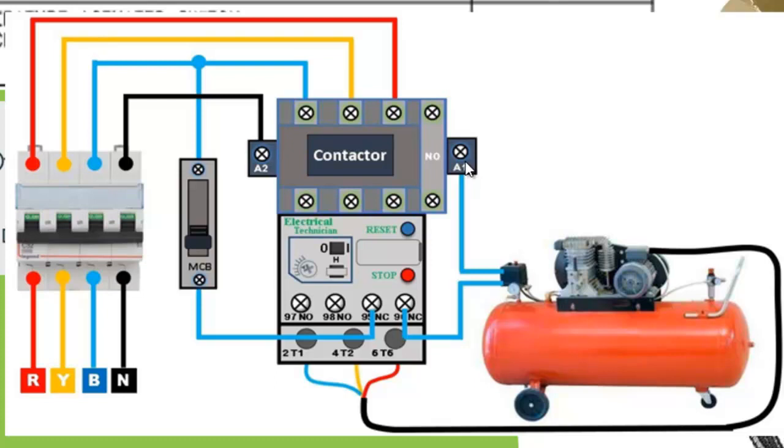It can be configured so that when the temperature drops to a level, the switch will close, the contactor coil will have the necessary signal and be energized, and that will close the contactor supply to the compressor motor, and it starts compressing again. Then the cycle will repeat.